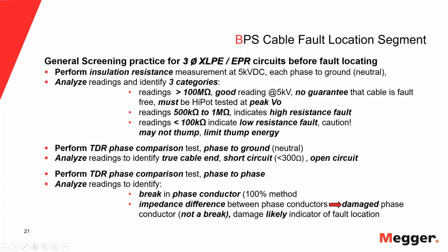Because we can do, again, with a TDR, we can do a phase comparison. So we connect phase to ground like we would normally do, and we can compare the three phases to each other. And what we're really trying to identify with that test is we're trying to find out whether we're really looking at the true cable end,